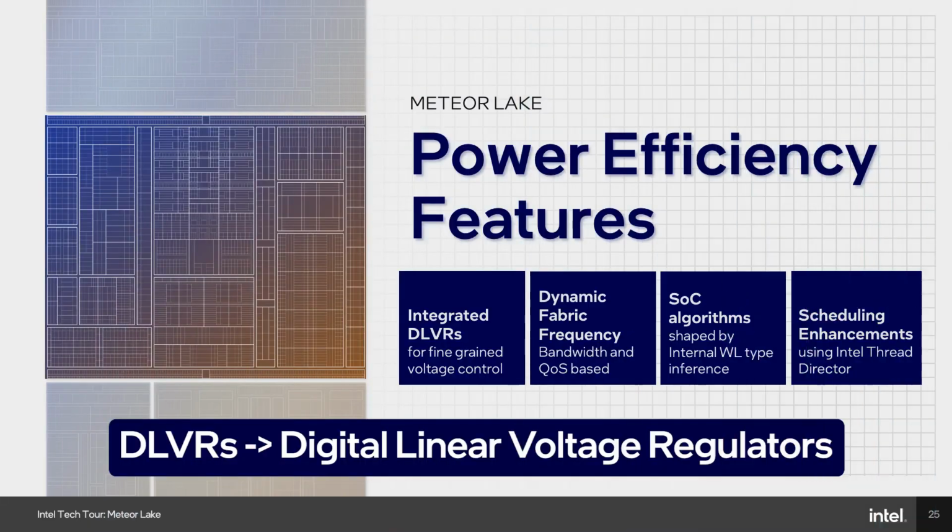So for Meteor Lake, there are a few things that we really focused on. The first is the DLVRs. We integrated DLVRs into Meteor Lake to allow fine power control of each of the IPs. It allows us to control individual tiles, but also to go to the IP layers themselves to control the performance of the IP and set the right optimization point based on the workload itself.